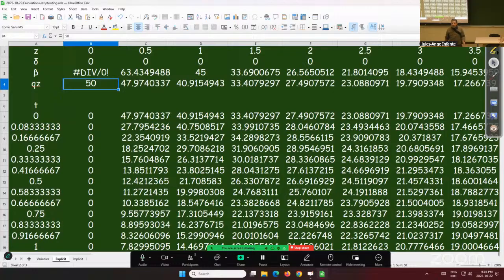Why would they only pick undrained? My guess is that they estimated the hydraulic conductivity of the clay, figured out how long they could keep an excavation open and stay safe. Okay, but that's based on samples, probably lab tests. The problem is that they missed the little seams of sand and silt that were in between. Oh, then water was just coming. That's the problem with lab tests.